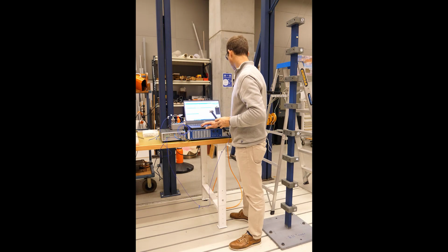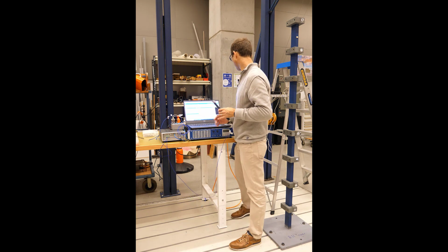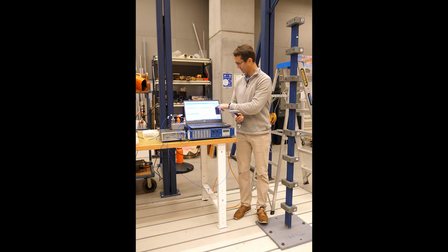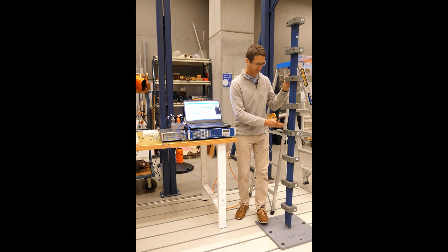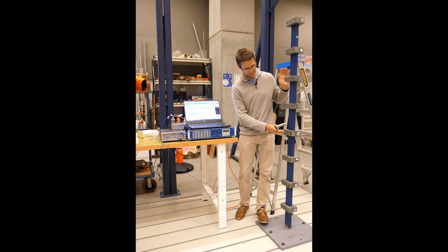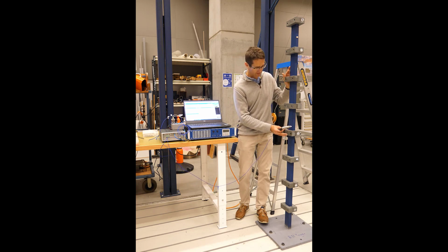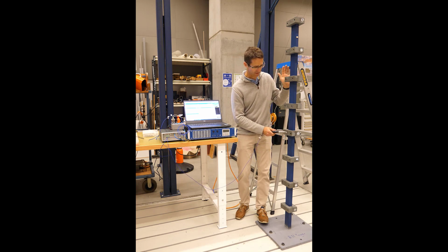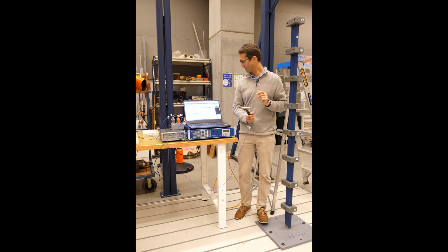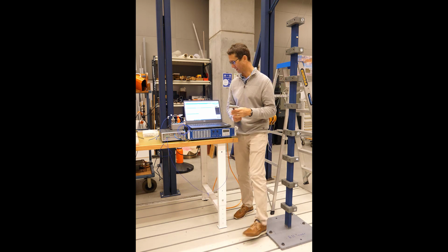I can increment and start keeping an eye on the name here that the FRF is going to be labelled with, making sure it is consistent with where I'm actually striking the tower. If I strike the tower at a different location to that which I've told the software I'm collecting an FRF for, clearly when I do the modal analysis I have a problem, because it's going to be animating a different part of the geometry with data from somewhere else, and we don't want that.